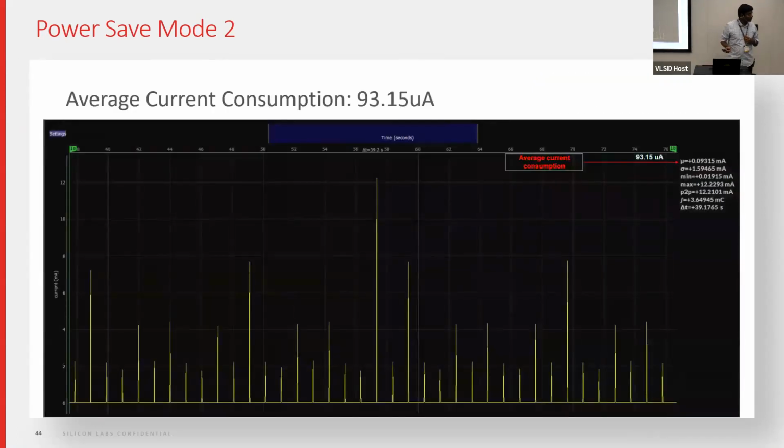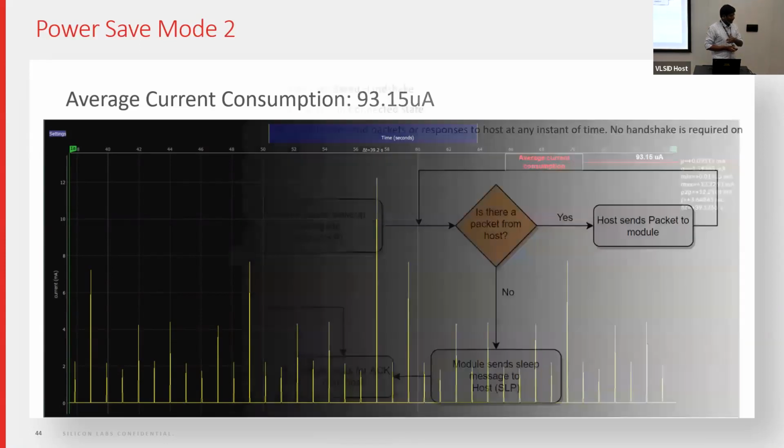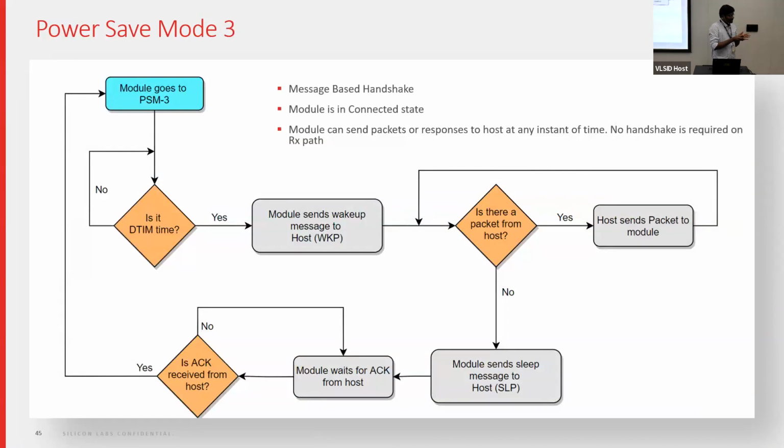I have one question. Sure. So what is the buffer time from getting the indication to sending the data? Do we have any time allocated? We don't have that, but whenever the AP has buffered packets for that particular client, the module will wake up at every DTIM beacon, and when the beacon is a DTIM beacon, the AP will transmit all the data to that client.